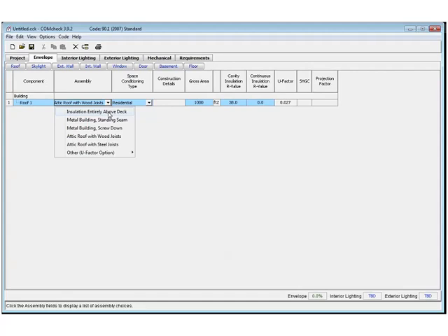And that would be continuous insulation, and that's your only option here. The U factor changed based upon the common construction, but then again, I'm going to need to make sure, since I've changed this, square footage is what I want it to be, and that I'm putting in the proper continuous insulation value that I'm applying to that insulation above the roof deck.